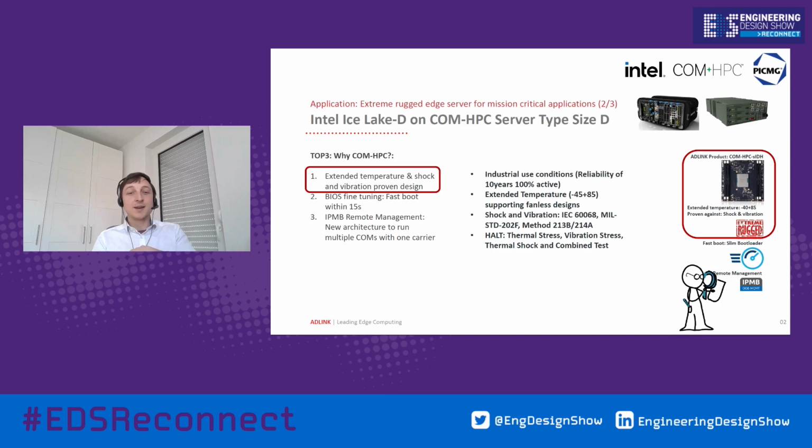And you might be wondering again, why don't they simply implement commercial off-the-shelf 19-inch server solutions? So typically, commercial off-the-shelf server equipment offers commercial temperature ranges only, meaning 0 to 60 degree operation in the best case. What is wrong with using this equipment at -20 or -40 degrees? It is simply not booting reliably anymore, which is the worst case for equipment which has to work 24/7 without